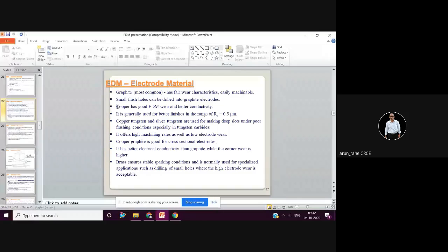If you mount one electrode, it probably goes for half an hour to 1 hour. So that's why it can be done manually. Investment in a tool magazine is not feasible unless you run the machine unmanned for one shift, sometimes two shifts, and sometimes three shifts also. There, yes, you can fix all the electrodes and leave the machine unmanned.